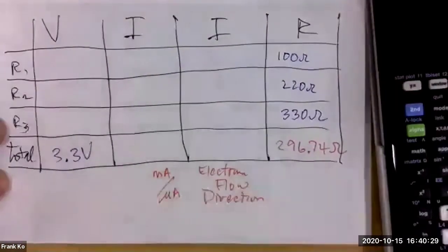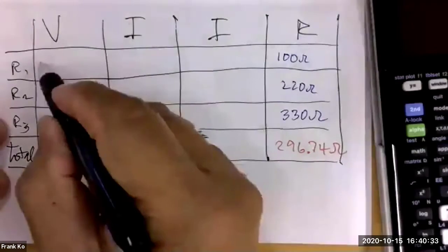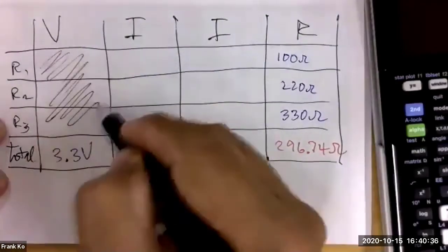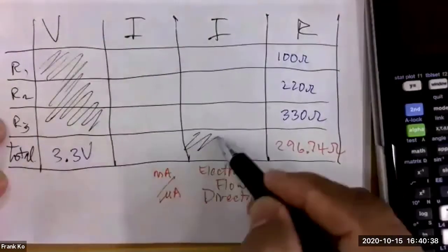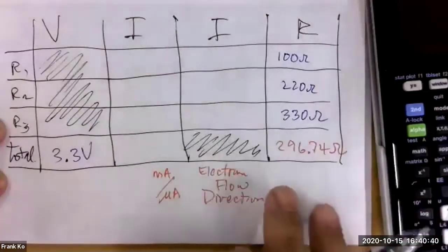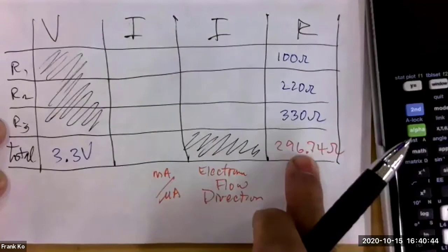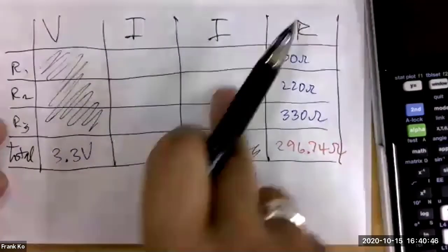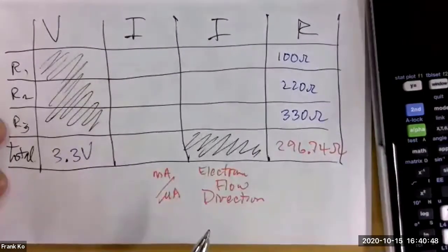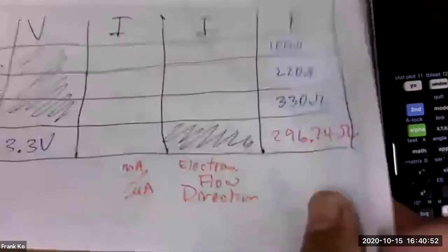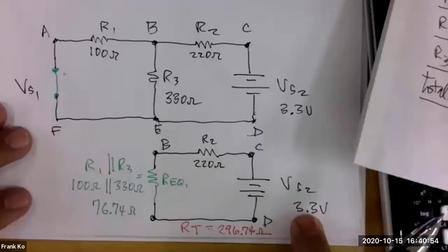And we said before, in this part of our superposition analysis, we can forego doing this particular sequence of cells, and we can forego this. So really, we need the total resistance and these 7 cells, okay? So do we have enough information to find I total? We have V total, we have R total.